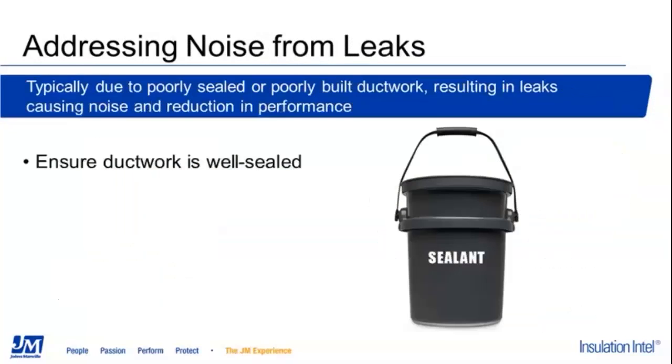And also, I want to talk a little bit about leaks. So leaks would be caused by poor workmanship when construction is done. It may just not be well sealed. So it's important to make sure that when you're doing final checkouts that you're listening for any kind of whistles or anything like that. So that would not only equate to better efficiency, but also helps acoustically to prevent any kind of tonal issues you may get from leaks.